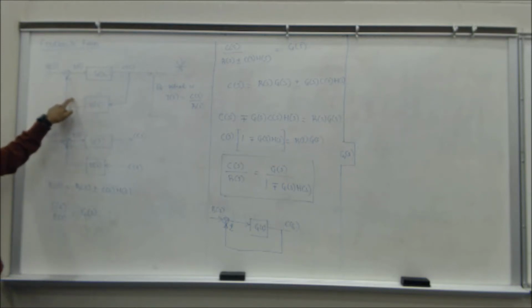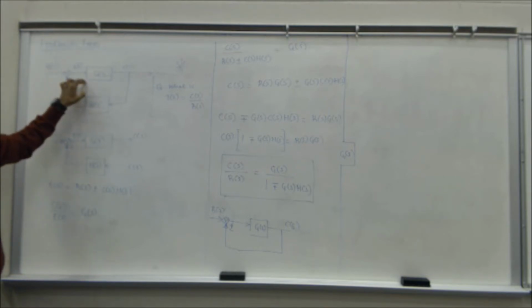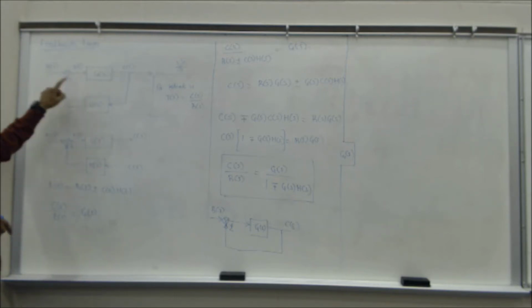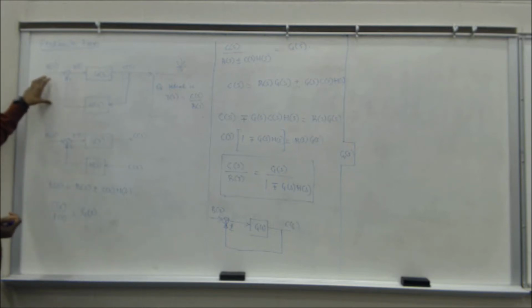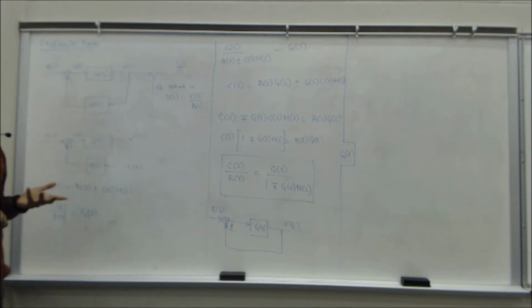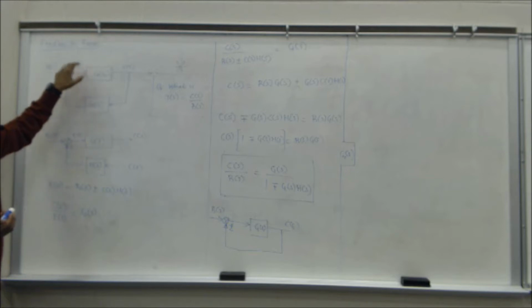You can name that signal. Similarly, this signal is a combination of these two signals, so you can name it. I just wanted to name it error signal, so I denoted E of S. It is an error signal because this is my input and this is my output. I'm measuring what needs to go in and what the output is. If my output is the same as the input, if I've already achieved the temperature, this E of S will be 0 and the system will shut down.